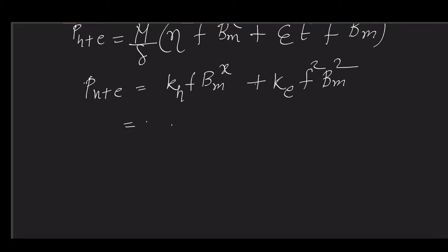need three values. What are the three sets of equations? Three different voltages and frequencies we have to consider, and we have to find three different iron losses for the same transformer under no load condition. We have to change the operating voltage and frequency three times.